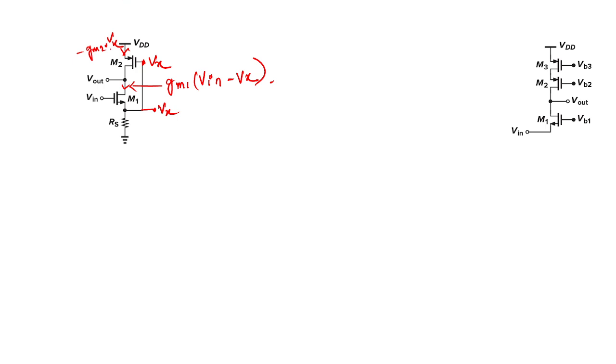Now if you consider R0 here, R0 is connected here, so the amount of current flowing in this direction is Vout by R0, and here another R0 will be present. The amount of current flowing in the downward direction is Vout minus Vx by R0. Now you need to solve this equation. So what equations are we getting if you write KCL in this node?